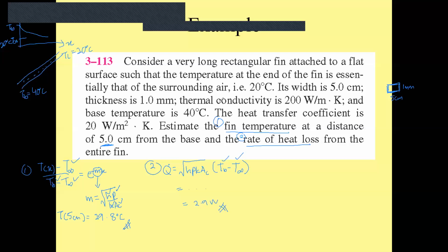The first one is it is very long. The second one is there is no heat loss at the fin tip, and then the third case, you have to know the temperature at the fin tip, whereas at the fourth one, you will have to know the rate of heat loss from the fin tip.